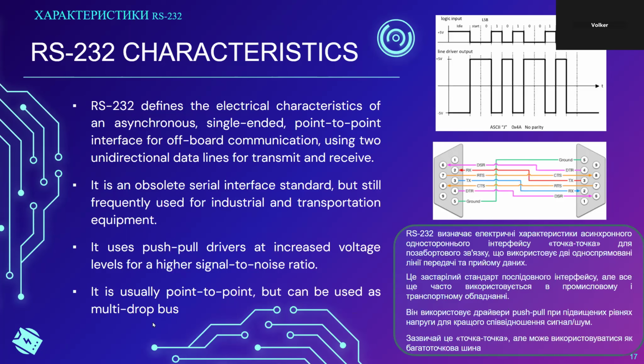Usually RS-232 is defined or used up to 15 meters of cable length. If you use a lower speed, often you can run it for a longer distance. But generally 15 meters, 20 meters is probably the longest that you should run an RS-232 cable. Beyond that, one should think about switching to a different type of interface.